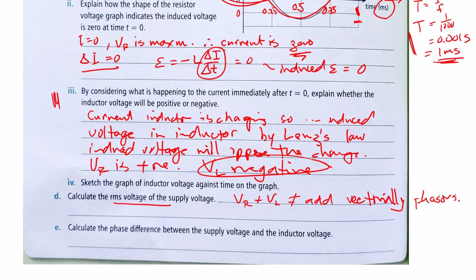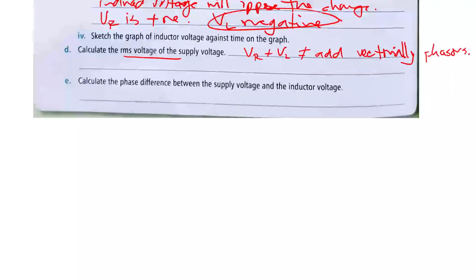So let's perhaps have a diagram of this. We've got the voltage across the inductor of 42 volt, and we've got the voltage through the resistor of 30 volt. And remember that the voltage across the inductor always leads the voltage across the resistor by 90 degrees. So there's our perfect 90 degrees you can see there.